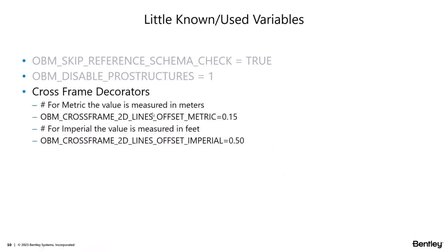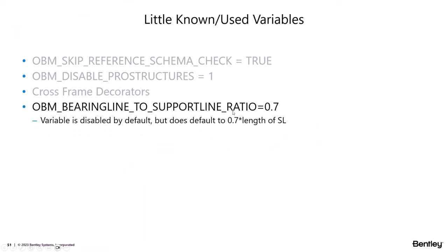Cross-frame decorators. So the 2D lines that are drawn, anytime you have cross frames that represent your stiffeners and cross frames, there's a simple little variable that's been around forever for setting the spacing between those elements.